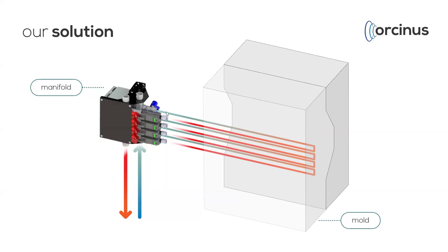When you're measuring only what's going into the mold, you have no idea what's happening inside. But we want to know, as I explained with the formula. We need to have a precise wall temperature so that we can say how long our cooling time is and what's happening inside the mold.